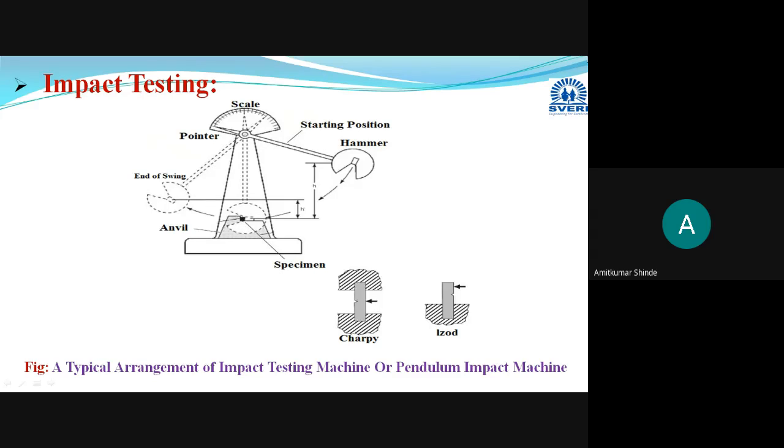In a ductile material, neck formation takes place and a cup and cone like surface is formed. If you see the crack point from the top, you will see two circles, which is the cup and cone appearance.